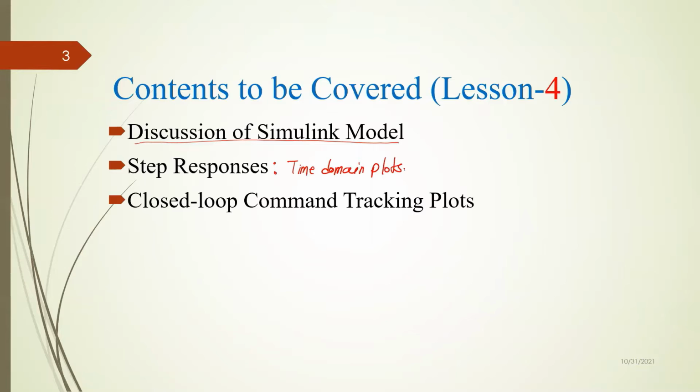And in the last part, we would also like to validate the current controller using closed loop command tracking plot, where we would plot our Bode plots, and this is our frequency domain plot. Okay, so these are the main contents for this video.